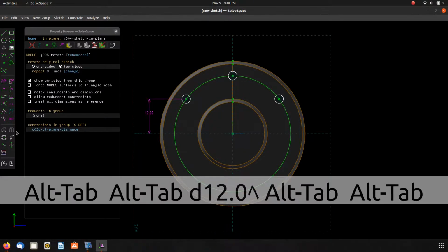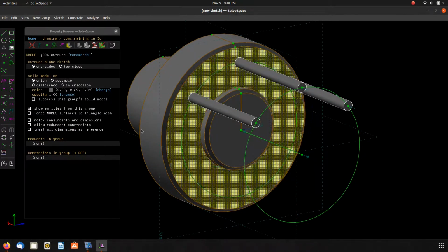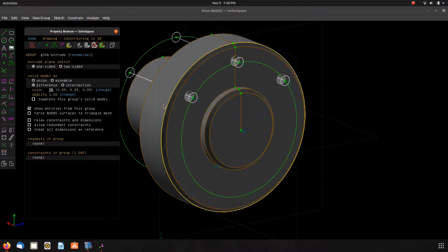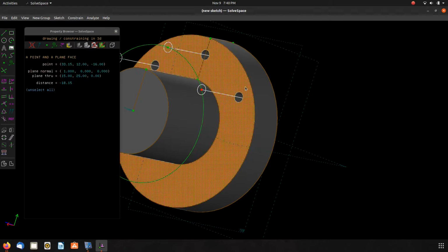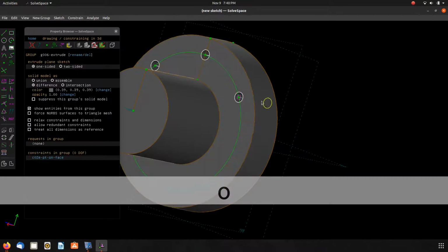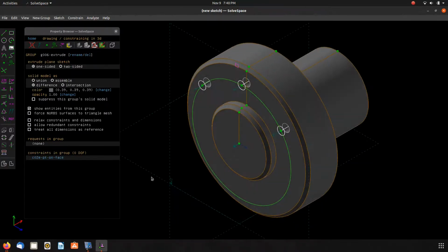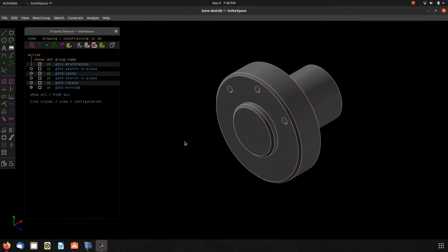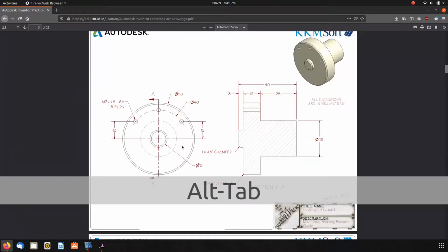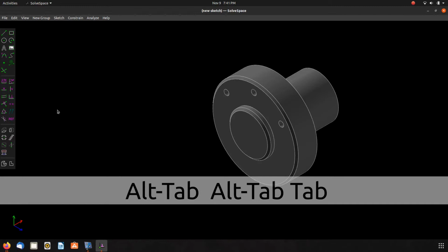We basically just made that a symmetric thing, dimensioned it to 12 millimeters. Since it's fully constrained, we'll make this a difference. We'll select that point, constrain it to this back face here, press O, and then we're pretty much finished. So we'll go home, hide all, and aside from that extremely large button in the front face there, and the wrong size diameter holes, it's a complete model.